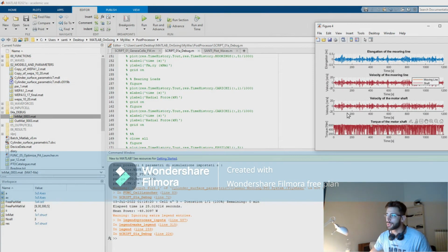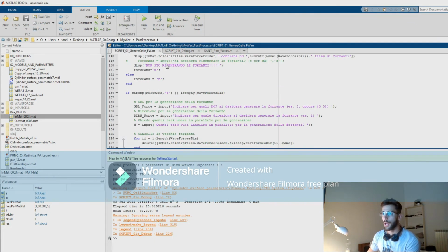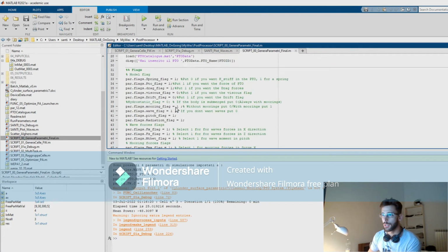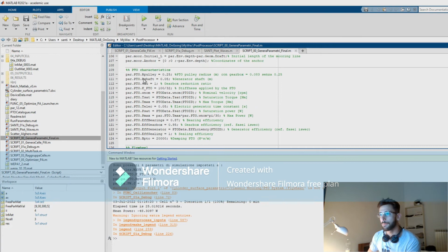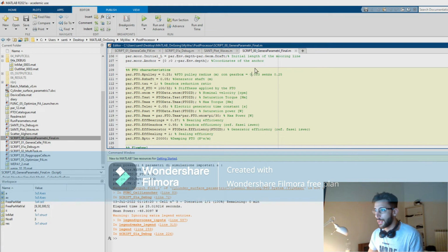Now here, there's something that should be changed, because in our case, we don't have a motor shaft, we just wanted the force, okay? So this is getting a torque, in Newton meters, but we just have to divide this by the input shaft that we have, that should be here. It would be the pulley, yeah, the pulley or the radius of the shaft. We should check it on the simulating model, but we have to apply one of these transformations.